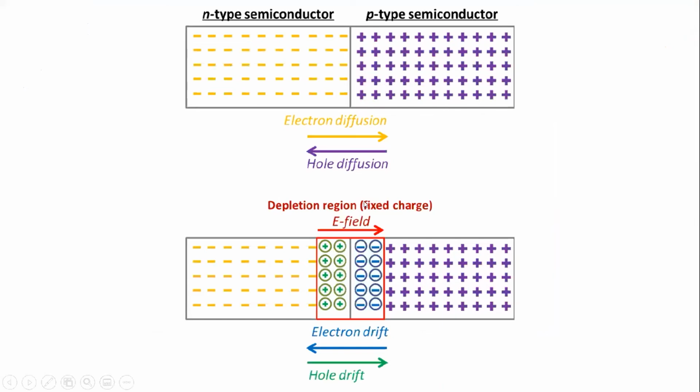So when these processes are happening, from the N type here the electrons start to diffuse towards the P type, and in a similar manner the holes from the P type start to diffuse towards the N type. Okay, and slowly what happens? There will be a region in the interface which is depleted, because there will be recombination when both are joined, as shown in the animation. So this is depleted of any free charges, so it is named the depletion region. Depletion region means depleted of free charges.